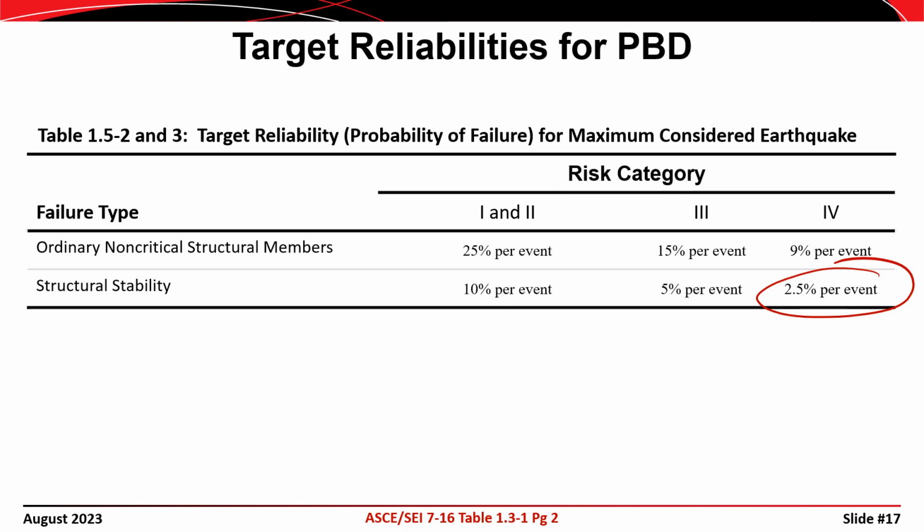And it just goes to the fundamental philosophy of design in that when we look at performance of a building on a day-to-day basis, we shouldn't have any buildings failing under normal snow loads, rain loads, live and dead loads, or even under routine wind events. But we're willing to tolerate the failure of a significant number of buildings under earthquakes, right? A maximum considered earthquake. Now, why is that?